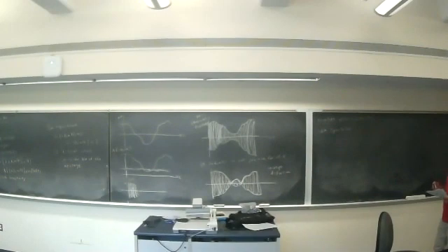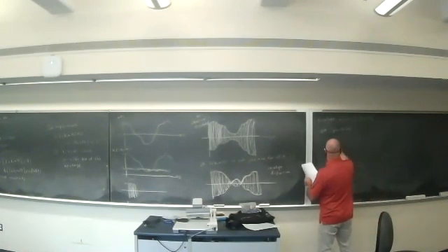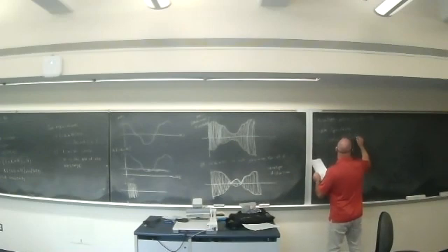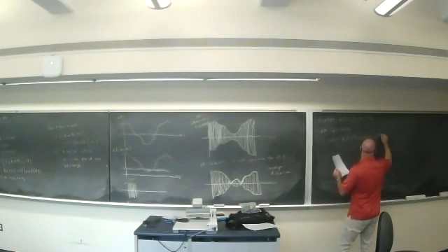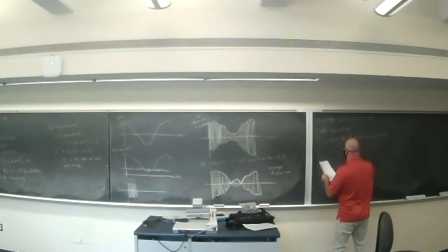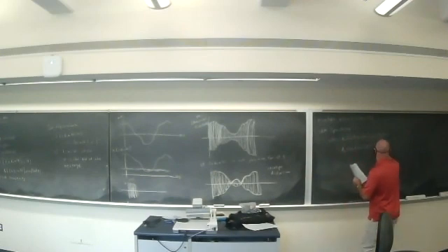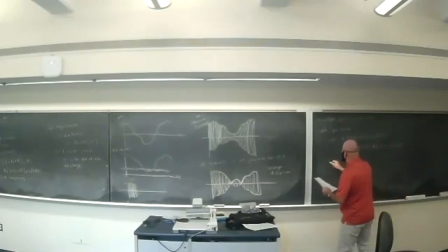Let's take a look at what happens in the frequency domain. Okay. s(t) is Ac (1 plus Ka m(t)) cosine of 2 pi fc t. Or just expanding that out, Ac cosine of 2 pi fc t plus Ka, I left out my Ac, Ac m(t) cosine of 2 pi fc t. Okay.